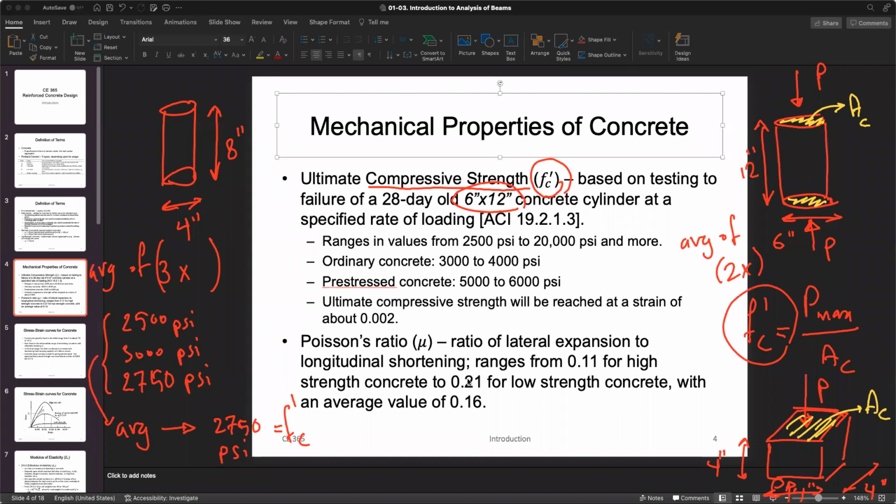Having this said, one important thing. This compressive strength of concrete, in 28 days, you are reaching almost a maximum compressive strength. 28 days from the time that you cast the fresh concrete. If you think about it, concrete is almost like a liquid. As time goes on, it gets stiffer and stiffer and stronger and stronger. At 28 days, you are reaching almost your maximum strength. That is your threshold or milestone, the time that I can load my concrete.